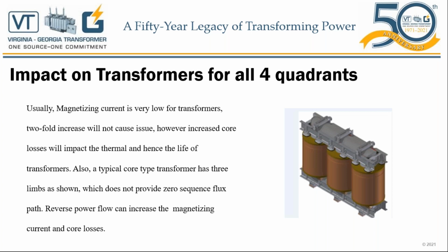As we all know, the major effect of temperature increase in a transformer is on the life of the insulation, which is why our transformers are designed to run at 65 degrees C with the average ambient that comes close to 100 degrees, where the cellulosic material, paper and wood that we use inside, will start aging faster. That's why keeping the temperature under control in a transformer is very important. And aged insulation means the transformer's integrity against short circuits and faults will have degraded as well. Temperature is a very critical phenomenon for the life of the transformer. Combine that with moisture and other effects, and we are basically talking about the life expectancy of a transformer.